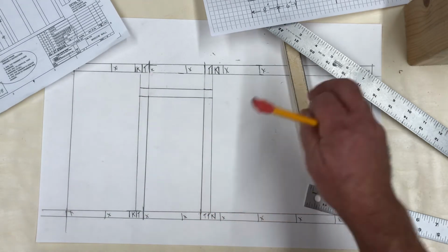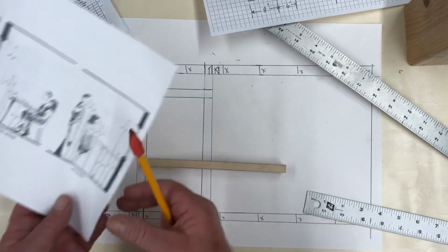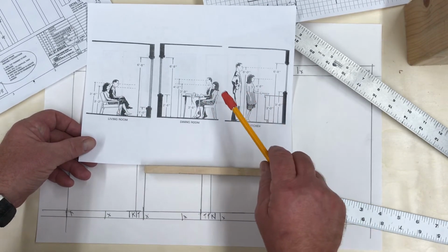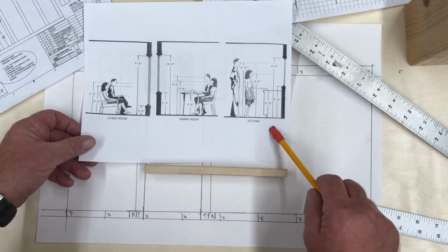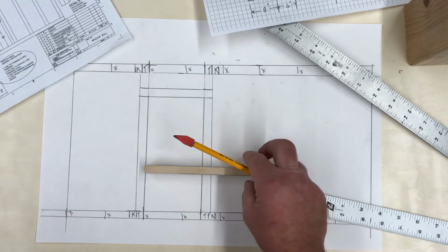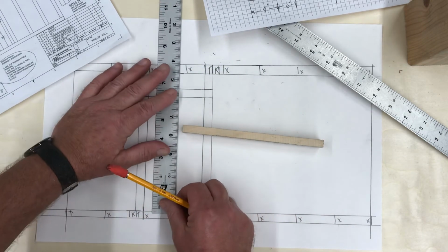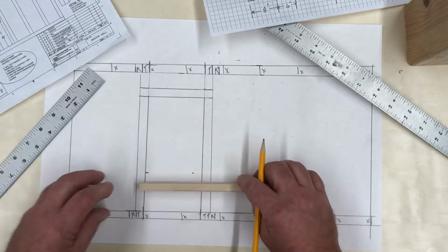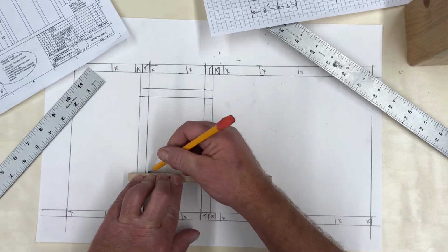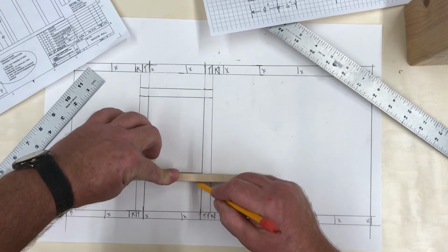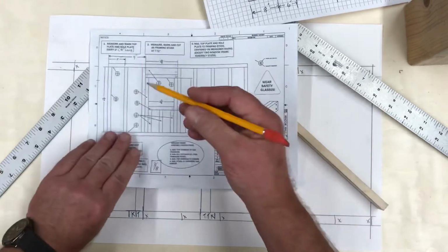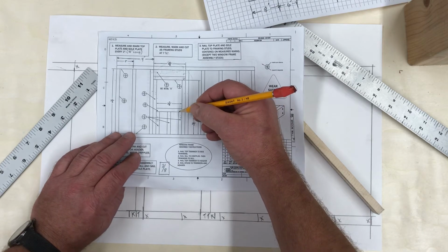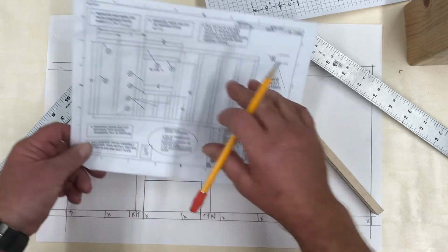Now, how high do we need to put in a sill plate for the window? Remember we showed this diagram before, with different styles and different heights of windows for different areas, like the living room, dining room, and kitchen. To make it simple, I'm going to come up 2 inches, and I am going to draw my sill plate. Remember, the sill plate goes between the trimmer studs. Take a look at this picture. This will help clarify where they stop and where they go. That's why this packet is developed for you.